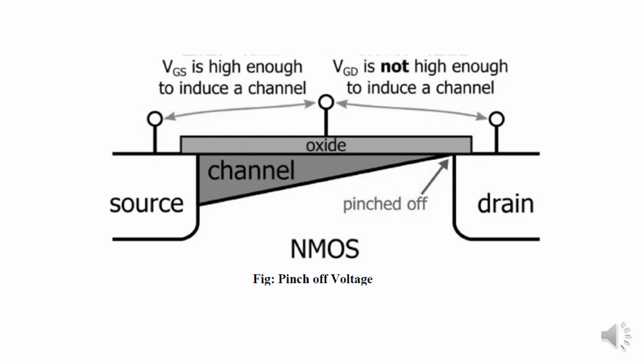It is one of the several short channel effects in MOSFET channel scaling. It also causes distortion in JFET amplifiers. To understand the effect, first note that a pinch-off of the channel is introduced. That is, the channel is formed by attracting carriers to the gate, and the current drawn through the channel is nearly constant, independent of drain voltage in saturation mode.